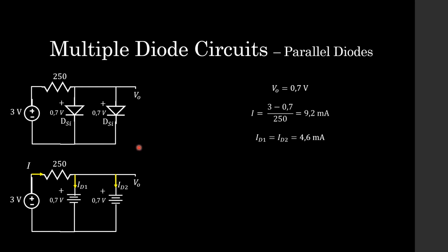So let's redraw our circuit, replacing our diodes with the constant drop model. So we have two 0.7 volt sources that we've replaced them with. Now students, what you need to note with this slide and this analysis is that this output voltage is one big node that is connected to the positive terminals of these diodes, or rather to the anodes of these diodes. Now, I'm sure you guys have remembered nodes and supernodes from circuits 1. Well, remember that stuff and take a look at this.